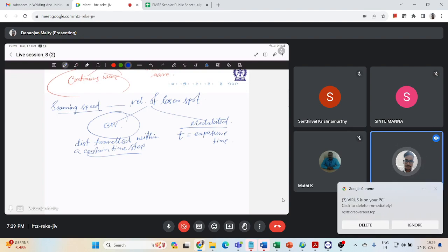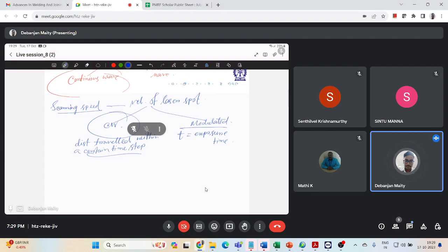Now, what are the different common defects in metal additive manufacturing? If you think in terms of welding, you can have porosity. The same things happen in additive manufacturing also. You can have porosity, which is an extremely common defect in additive manufacturing, right? These mechanisms during layer deposition are driven by temperature gradients, capillary forces, and gravity. Porosity is very much obvious in any kind of additive manufacturing. Then you can have lack of fusion during the printing process. Then you can have residual stress and gap formation. Those things are there, right?